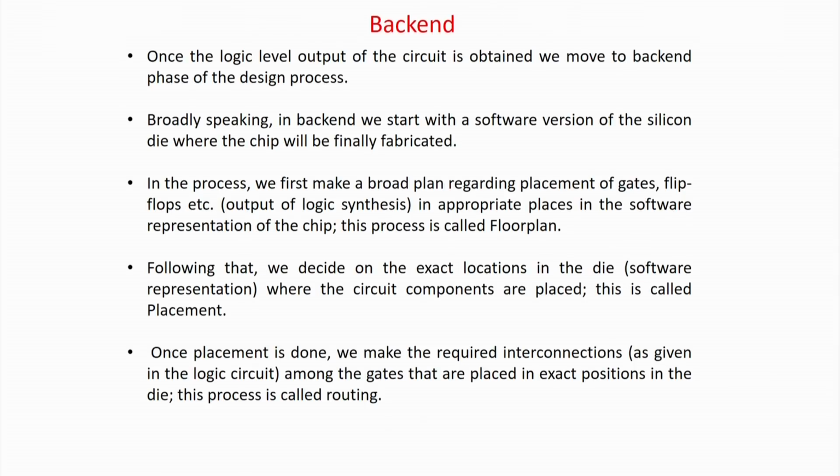Then once the gate level is done, basically you have to fabricate the circuit in terms of layout. So there will be a die, so you will have some rows and columns. So the gates have to be placed, and finally that is actually called the floor plan. Wherever which gates we will put, where will be the memory blocks. So broad level placement we do about the gates, which is called the floor plan, and then finally all the gates will be placed, which is called the placement, and finally based on the requirements of the circuit they have to be properly connected, which is called routing.